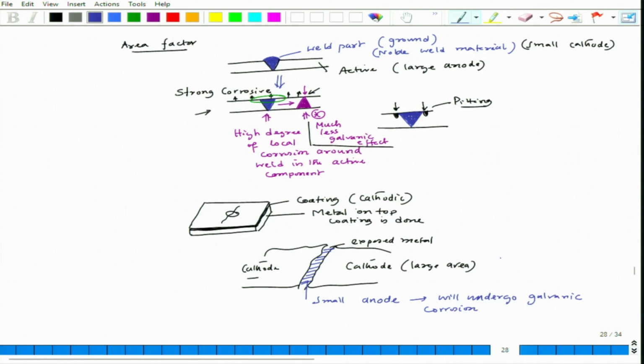So, cathodic reaction, let us say if it is in moist environment, so then this reaction would happen. And here, let us say if it is iron, this would corrode. So, this is a typical example if we have tin coating on iron or steel, okay, and let us say carbon steel which has no passivation tendency, right. So, this is another part.